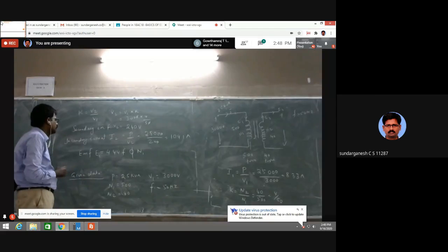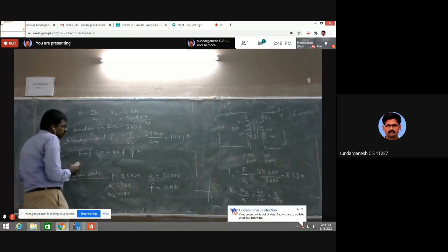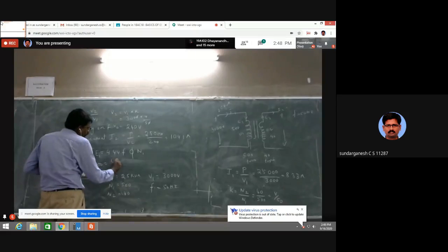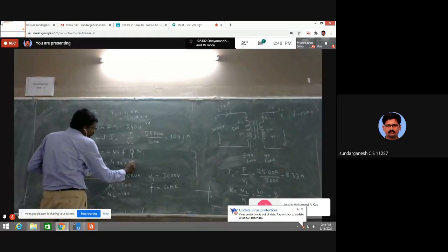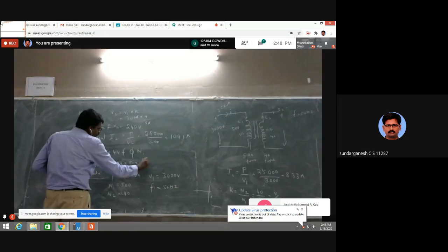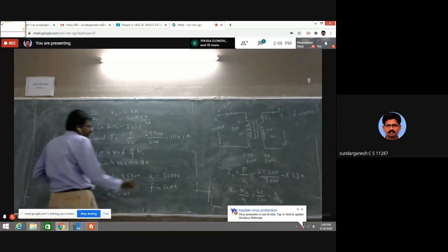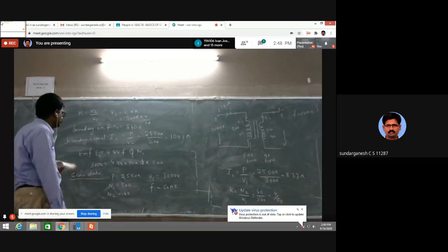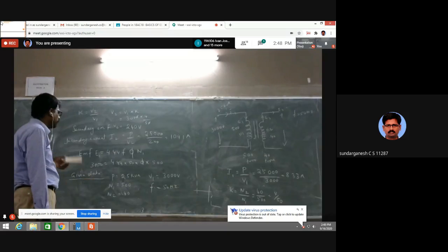Okay, so I am taking E1, the primary voltage, so I am taking N1. E1 is 3000 volts, N1 is 500. For E1, 3000 equals 4.44 into F, which is 50, phi I don't know, N1 is 500. Now we have to find the phi.